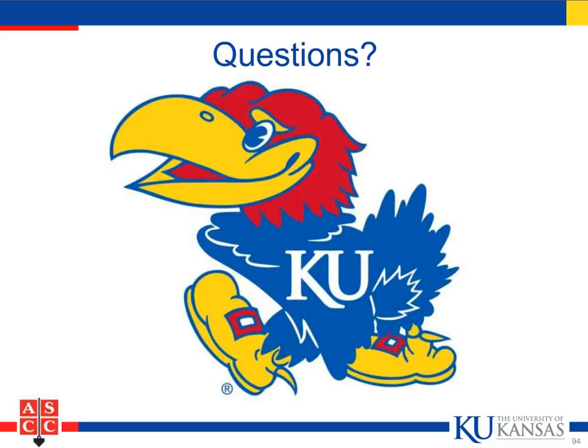And then my second part of that question would be, what about the old tampers or the jitterbugs and the hand tampers that people have used over the years compared to the vibrators? Okay, I don't like jitterbugs at all, and some folks may swear by them, but I don't like them because they end up knocking the coarse aggregate away from the surface. And what you really want is you would like your concrete to stay as uniform as possible.